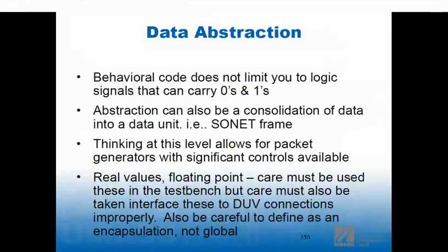Then I would have to write a directed test case, a sequence of instructions that would specifically, and you can copy this out of the textbook, cause a data hazard that would make that forwarding signal go active. I'd be pretty suspicious if that happened, but still, right? That's the kind of thing that constrained random stimulus and functional coverage tells you to go and write a directed test for.